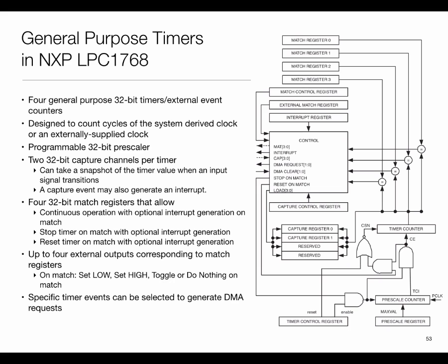Whereas if I was sending things as an 8-bit number, then I can keep changing it every clock cycle. So basically, if I have signals which need to change very rapidly, then I should use the bit parallel approach. But if on the other hand, I'm looking at slowly changing signals, then I can get away with a single value. So literally a PWM thing is nothing but a very fancy way of serial communication. Okay, that's what's happening. So it's temporal resolution, which is kind of the main thing.